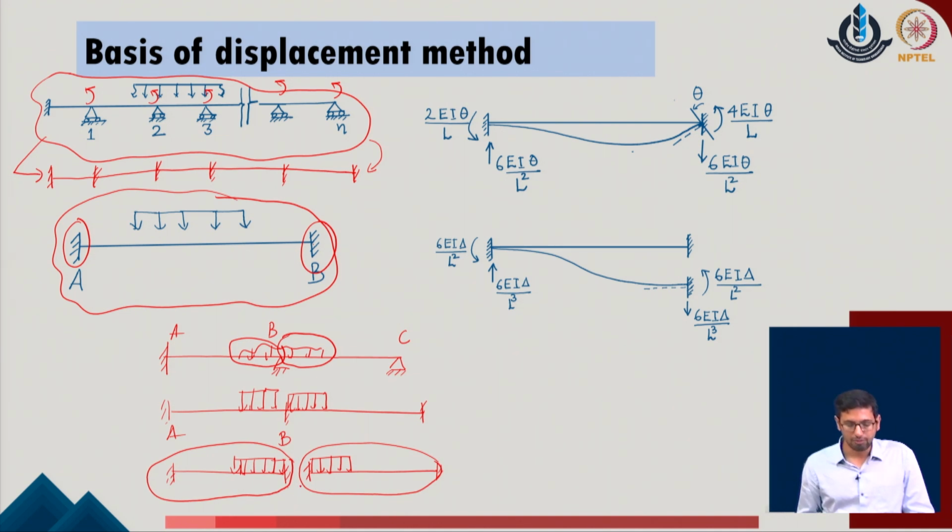That means the joint B will have some common reactions appearing from both sides, but as long as we go with a multiple support system where we have restrained the system and considered a load which is active over here, the influence of this load will only be felt in the span on which it is active. Any of the other spans will be completely free from the load active on this given span, and this is one of the main classifying criteria where we can describe the support reactions for these fixed ended systems very easily.